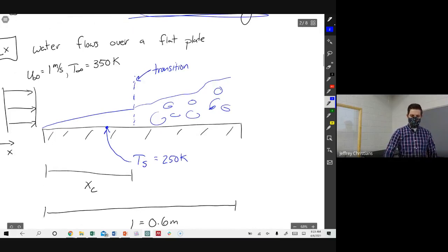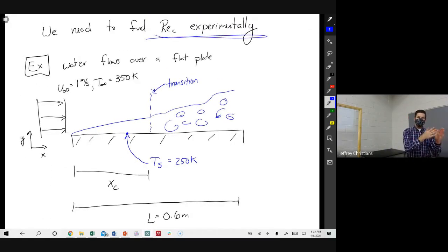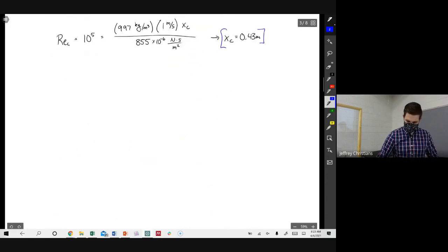When we're figuring out convection, we have to treat those two sections as distinctly different, because the dynamics in those sections are totally different. So we're always treating the laminar region and the turbulent region as two separate things.